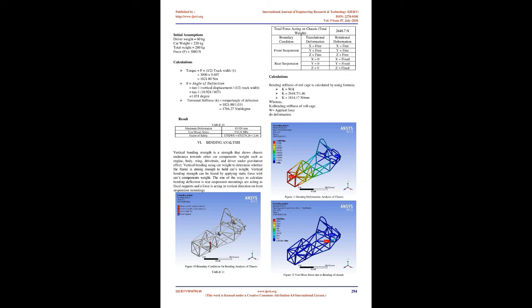This approach adopted in finding an ideal stiffness focused around finding the least stiff the chassis could be before major performance or handling losses would arise. This method was chosen because stiffness is so closely related to vehicle weight, and for a Formula FSAE vehicle, weight is the most sensitive parameter on the car.